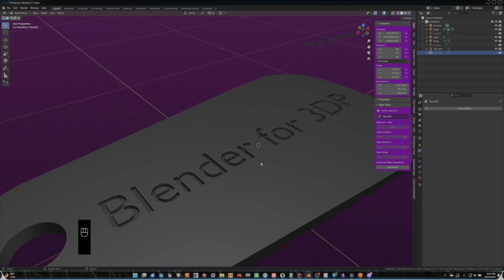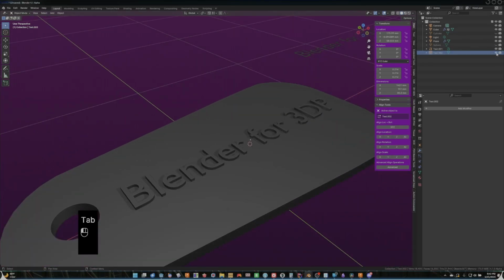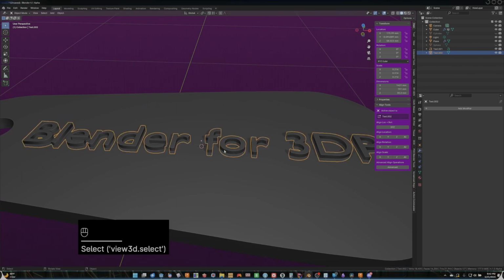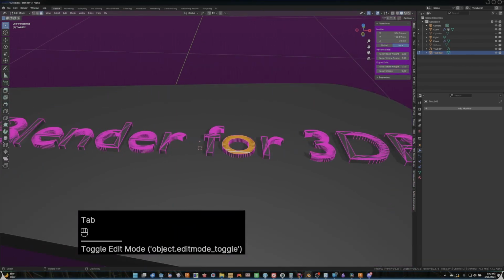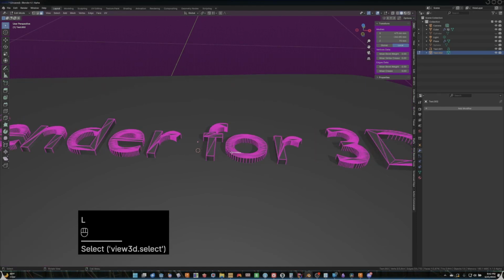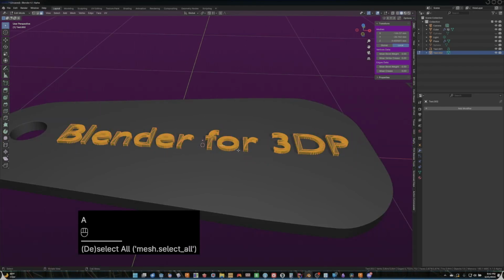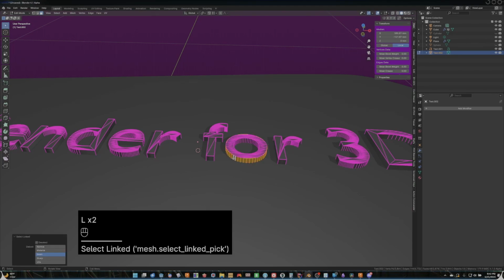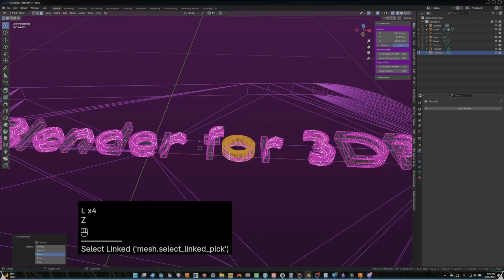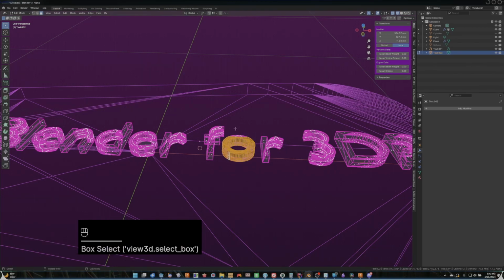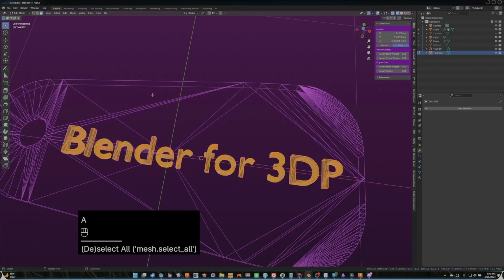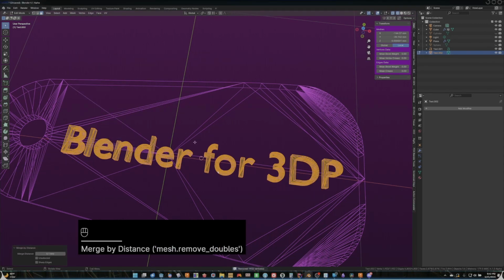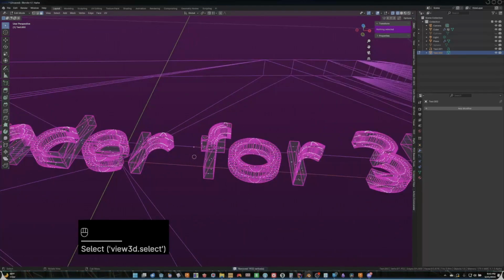That's decent. Now, sometimes you have an issue where your text has inverted normals, and I'm just going to do that for you really quickly. I'm going to merge, and I just showed you why you want to merge everything, because I tried selecting a whole letter and I got a face instead, or a set of faces, right? I don't want to have to manually select everything. I don't want to have to switch to wireframe and then try to select just the faces I want from that specific letter if geometry is too close. Instead, I'm just going to select everything, mesh, clean up, merge by distance, remove 1932 faces.